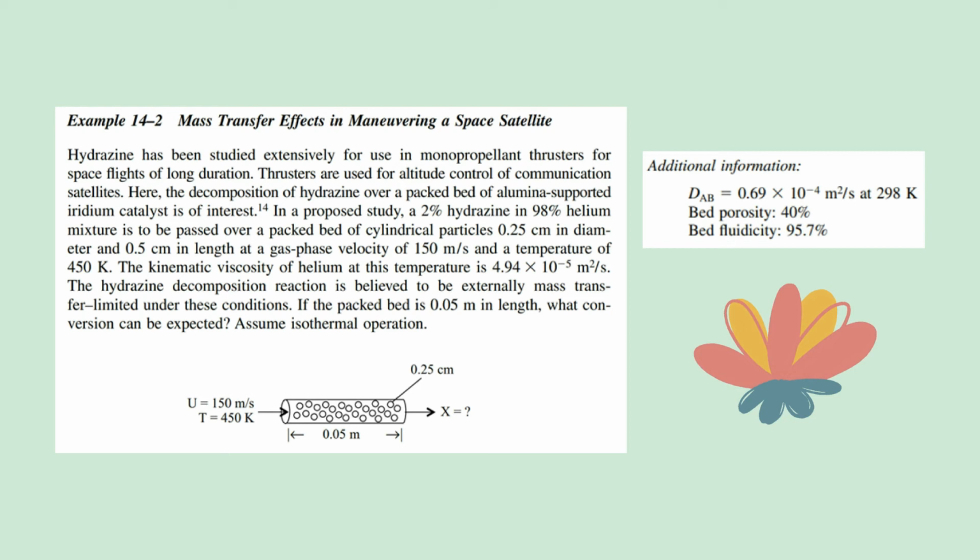The kinematic viscosity of helium at this temperature is 4.94 times 10 to the negative 5 meters squared per second. The hydrazine decomposition reaction is believed to be externally mass transfer limited under these conditions. If the packed bed is 0.05 meter in length, what conversion can be expected?